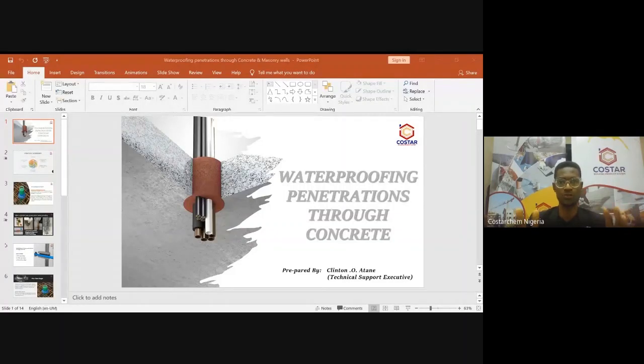Once you've fitted your formwork and arranged your pipe setting, ensure you use a plumb to get the best angle for your pipe fittings. I've seen jobs on site where they had some challenges with the degree or angle of the pipe after casting.